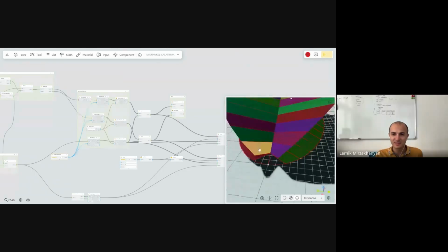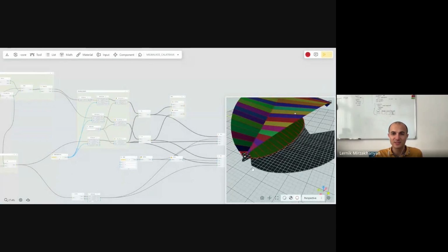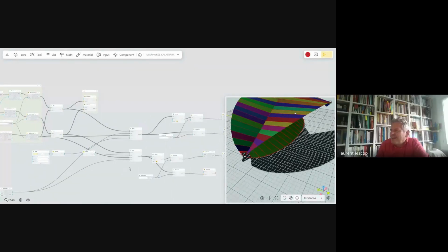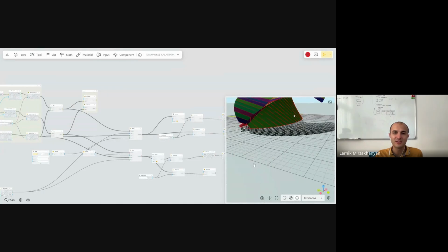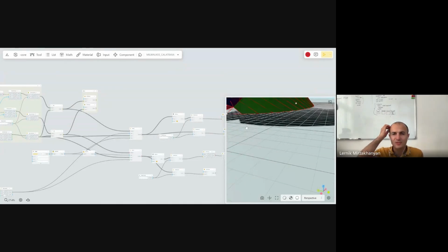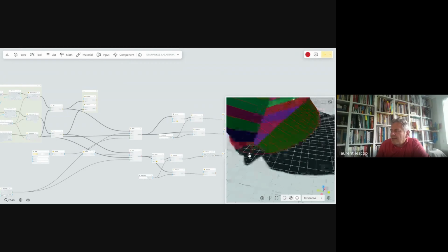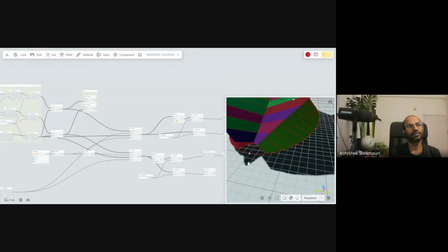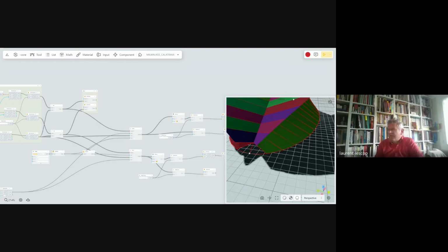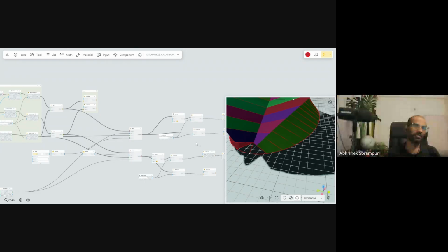Because the last point is the first point, it wouldn't loft there. I guess it wants a curve, it can't loft. Or can it? Is there a way to loft to a point? I'm not sure. I don't think it will work because one point is common over there. Yeah, that's right. But anyway, I think this is what the actual model is also like. I mean, it doesn't close completely. There is a gap.